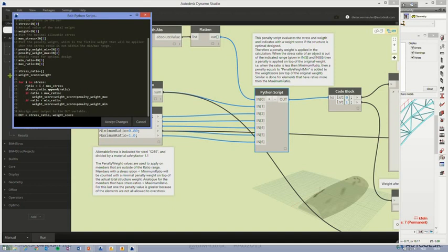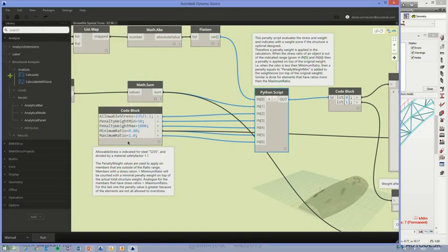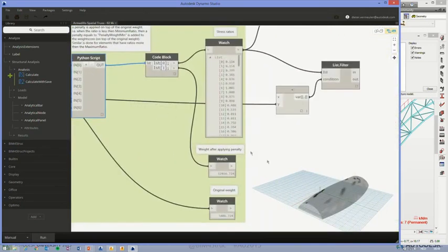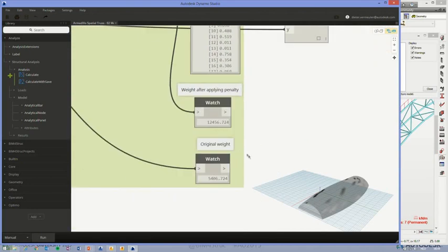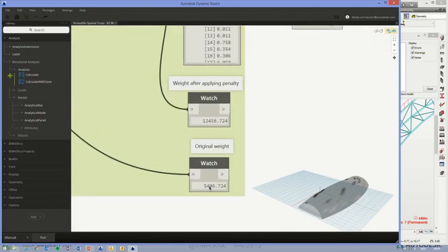Okay? So now these results are brought into some evaluation routine. What this evaluation routine will do is take the values and convert them from Newton per square meter to Newton per square millimeter, so that's just a simple calculation in here. It will convert Newton to kilograms because I want to have the weight, not the force. Then it performs some summarize formulas on it, and at the end you get a result in here, which are all the stresses in that structure.